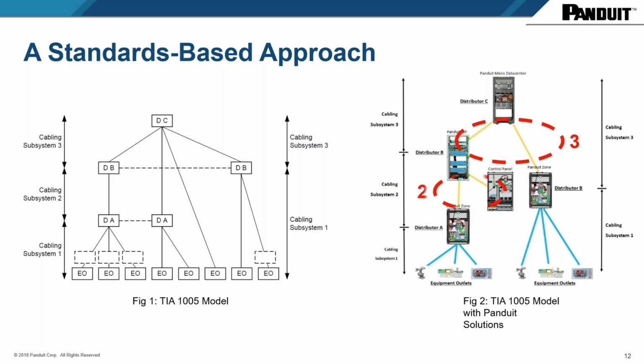And as you go down in the architecture, between distribution frames and zone controllers and zone enclosures, the MICE category might be at a higher level, and you need to make sure that your cabling can withstand those environments. And the run there can be fiber as well.